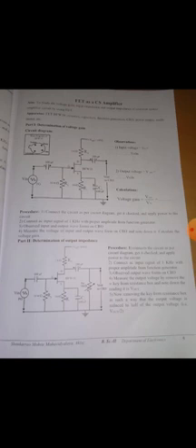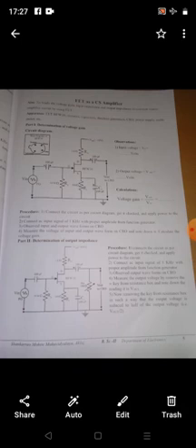Then apparatus of this experiment: FET BFW10, resistors. In this experiment we use 3 resistors. Then capacitors, we use 2 capacitors. Then FG means a frequency generator or function generator to give the input frequency. Then CRO, cathode ray oscilloscope, to display the output waveform of this experiment, meaning the observations. Then power supply, we use a 10 volt positive power supply. Multimeter for the output resistance measurement.